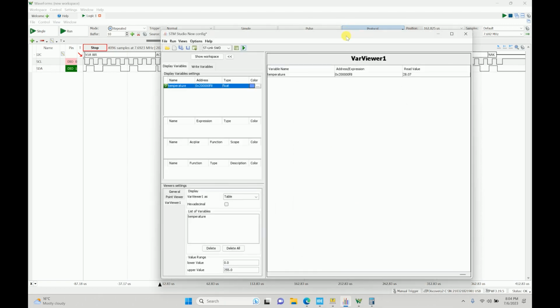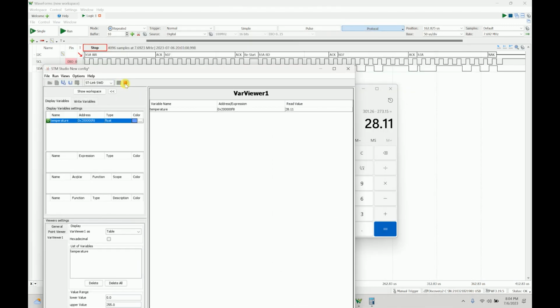And then when I come over here, I play it. So roughly it's a real time thing. I took this value of 28.11 degrees Celsius a time before, and then I just took it right now. So this is how it all makes sense. You read the data, you shift that data, you decode that data with the value that is given in the datasheet, and then you actually get that temperature in degrees Celsius from all that raw temperature.